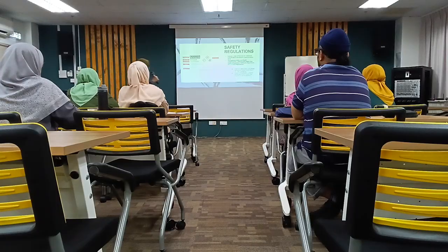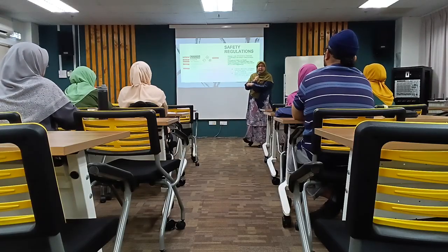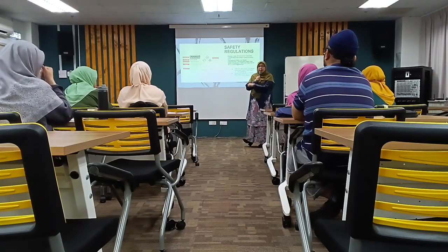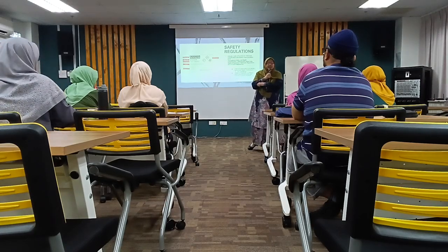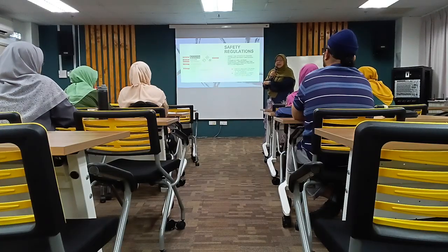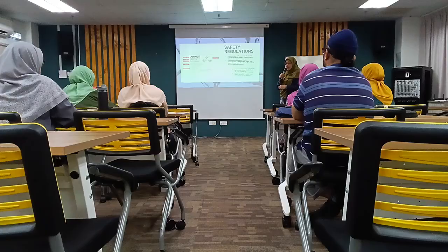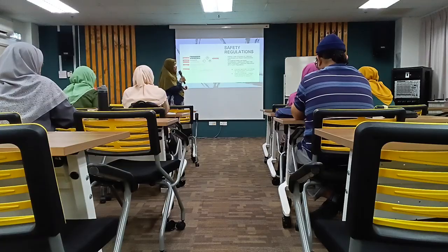So if, let's say, you receive a bottle without any of these or lacking any of these symbols, you are not sure what the status of that particular chemical is, because we don't know what the dangers are, we don't know what the possible hazard statements are. So please make sure that whenever we receive chemicals from a supplier, these are actually complete.